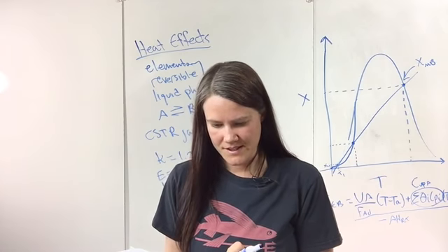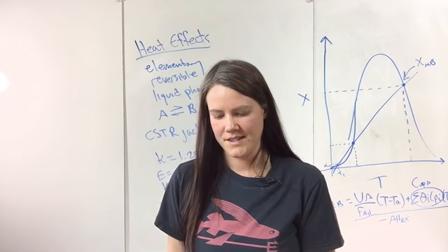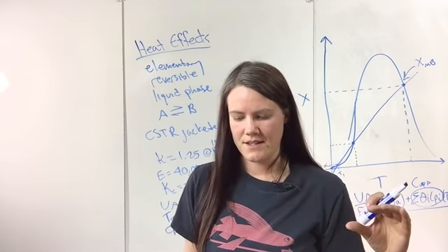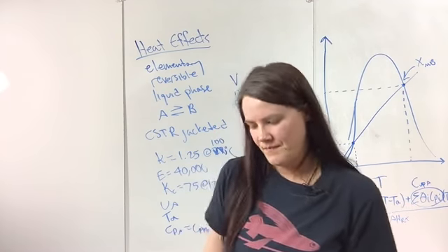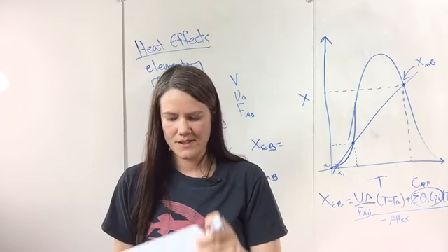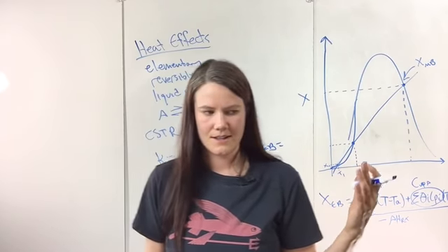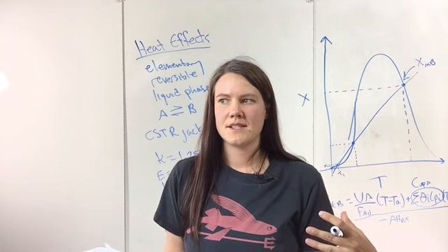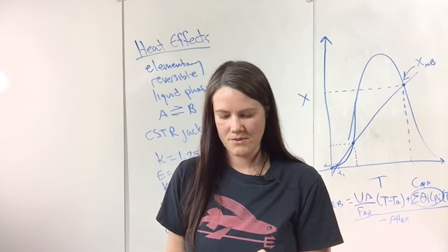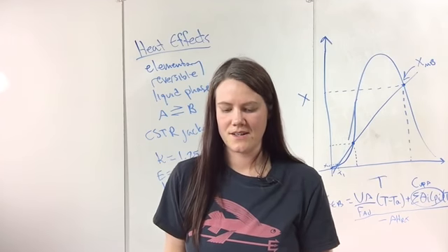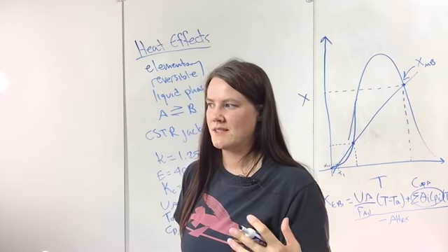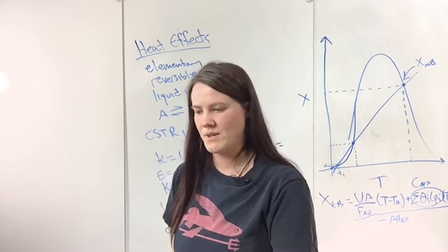And then the next one is the diffusion in the catalyst. That's where you have a catalyst, and the reactions we've been doing so far, we've been assuming that they are ideal. But really it's not ideal. So what you're doing when you calculate this effectiveness factor is saying, okay, it's not ideal, so this is what I actually got, and this is what I would get if it was ideal.